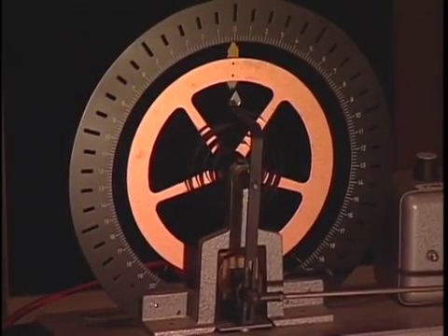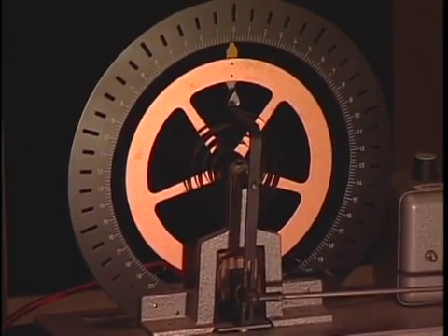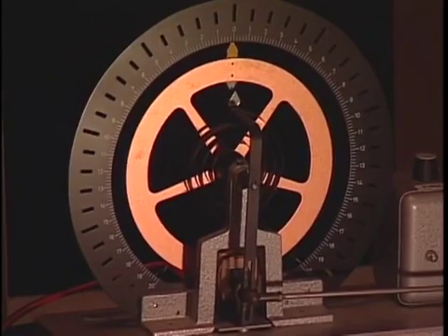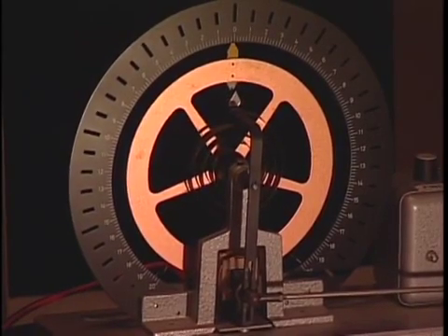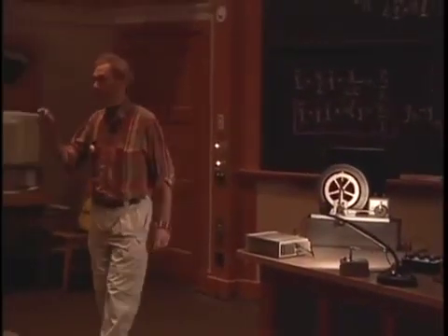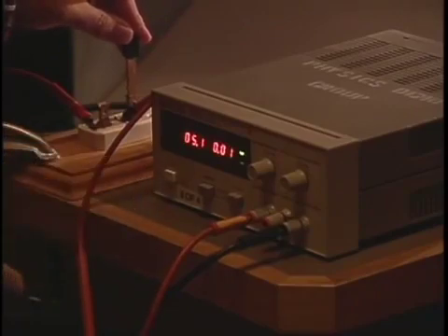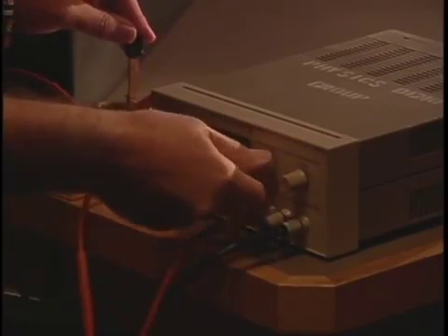But if I go to the point where you just don't smell smoke, then you're still underdamped, but you get a huge amount of damping. And the reason why I can say with confidence that it's still underdamped: I release it at 0 speed. And if I release it at 0 speed, and if it is overdamped, it can never overshoot. And yet you will see that there is a minute overshoot. So it is still underdamped, but it's getting very close to being critically damped. And so I will jack this up to the maximum possible.